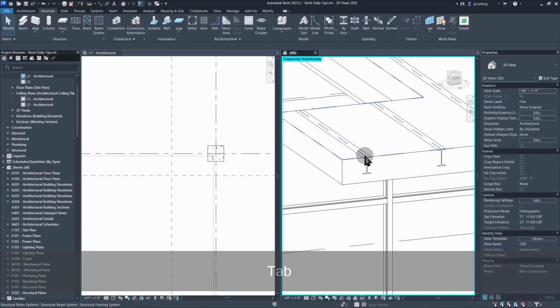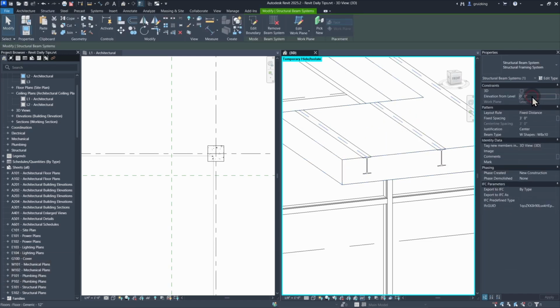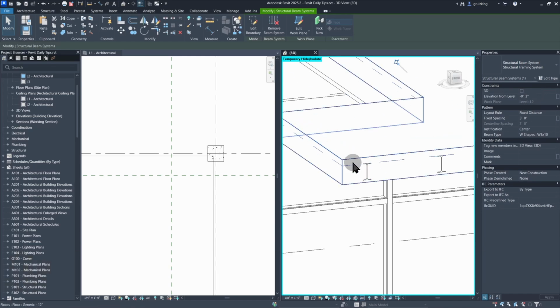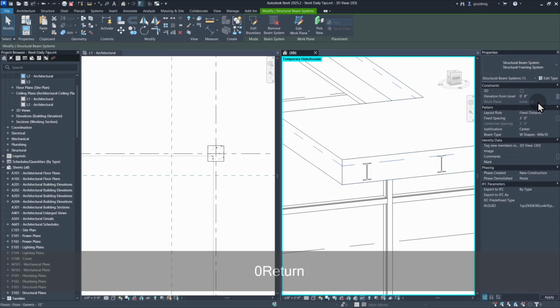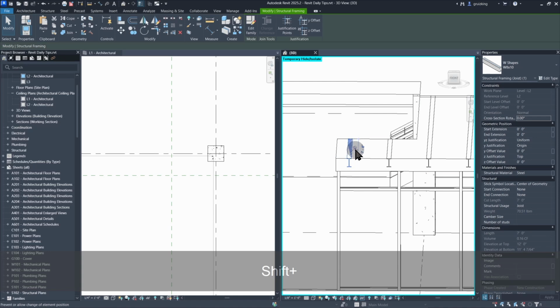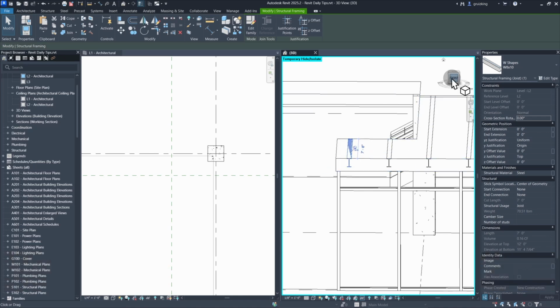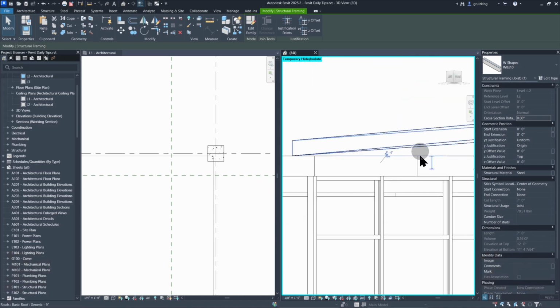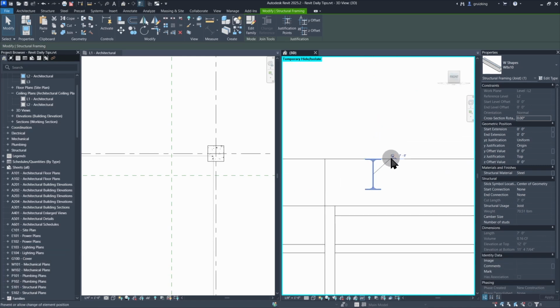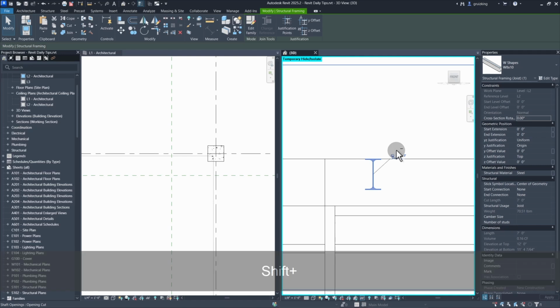Now, if I were to select the beam system, I can say, okay, go down something like 3 inches, and then they'll be in here, maybe accounting for some sort of metal deck or something else, depending on what the floor structure here is. One other thing I can do if I reset this back is, let's say that I needed this to actually be at the edge. Let's orient my view here. Actually, that doesn't work. Front. There we go.